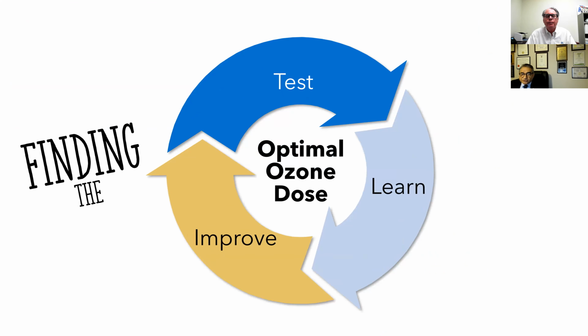The new approach which we used in the design for the plant is to introduce ozone for the oxidation of arsenic and manganese, which was based on the findings we had in the pilot study. And we continued to work in order to improve the quality of work and get an optimum applied ozone dose. Next slide, please.